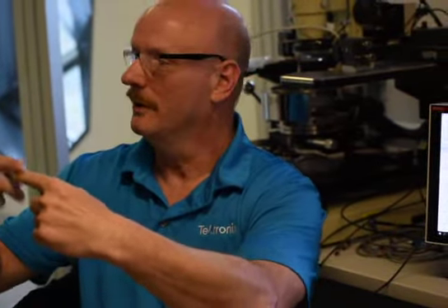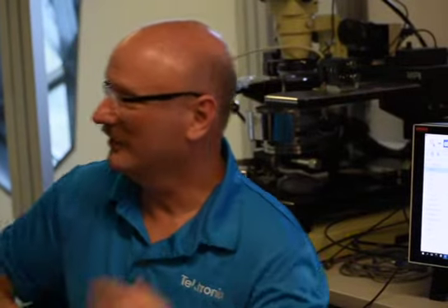So you can tie SMU1 directly to SMU2. You can drive SMU1 to 200 volts, and SMU2 will measure that 200 volts and that current for you. It can handle it. Whatever it can source, it can sink. So from that respect, you can't damage it, right? Whatever you can source out of one SMU, you can measure out of the other.